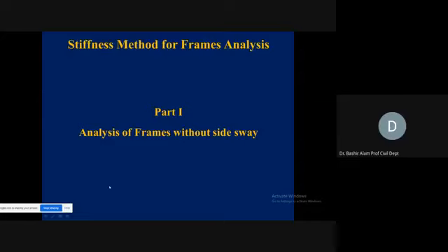The complication is that when you have displacement, additional kinematic indeterminacy comes in. Because of this additional kinematic indeterminacy, the kinematic indeterminacy of the structure will be higher, with more computational load, and because of more computational load, more complexity also.